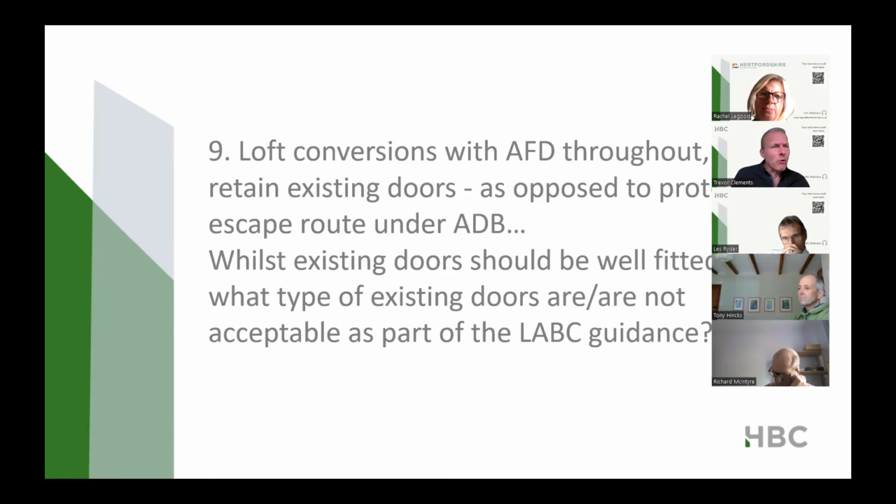Well, this brought in a lot of debate. At that time, we'd just seen the need for self-closing devices to be cancelled on fire doors in loft conversions. Older people amongst you remember when we used to have those. So, you know, an open fire door is no good at all, is it? And if it's not got a self-closer, it's more likely to be open. So this looked like a good option, but people were misapplying it.